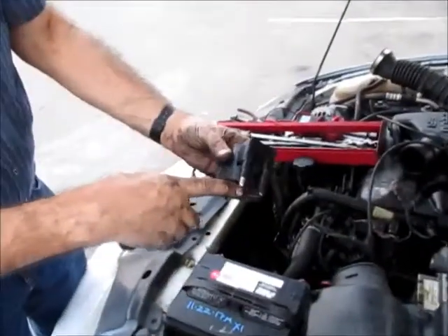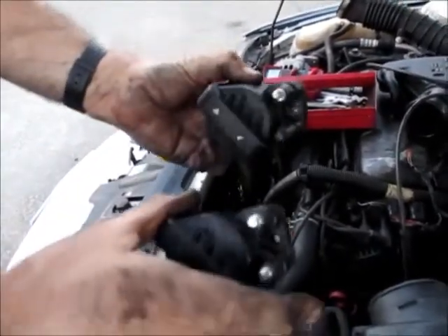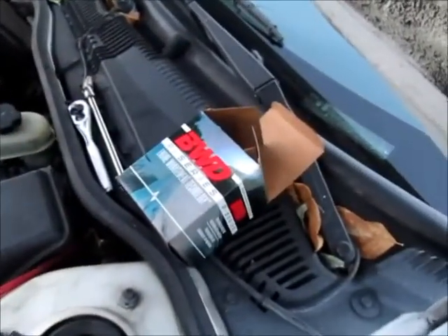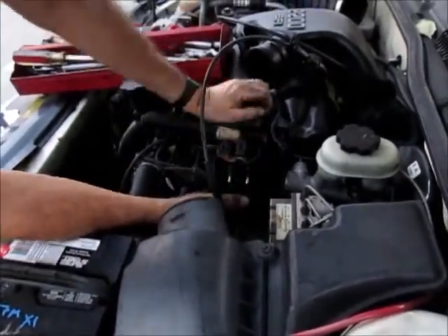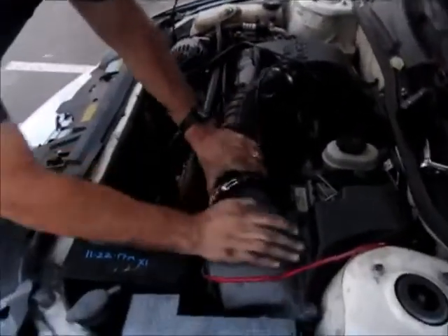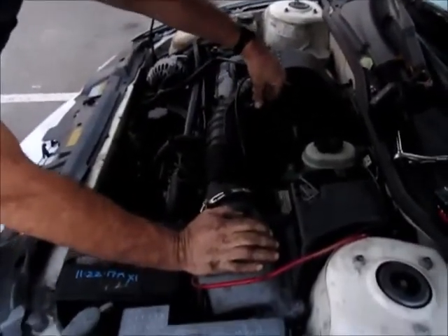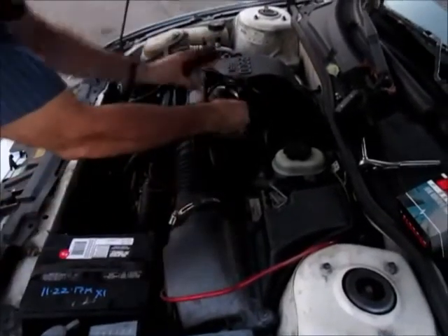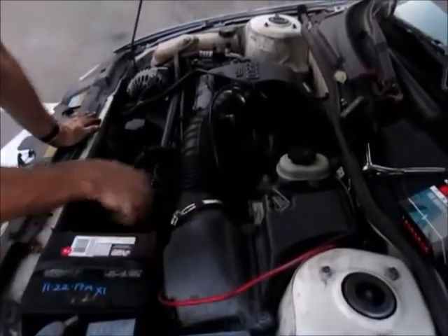So here's the bad coil, and you see the terminal wasn't firing anyway, and it might be due to corrosion. But we're just going to replace it with our replacement BWD P series coil. So just doing the final finishing installation of the coil. Make sure your intake air temperature sensor is connected. This doesn't have a MAP, I think, so you don't have to worry about that.